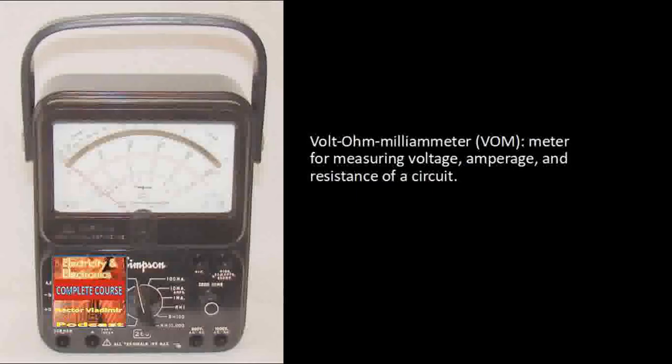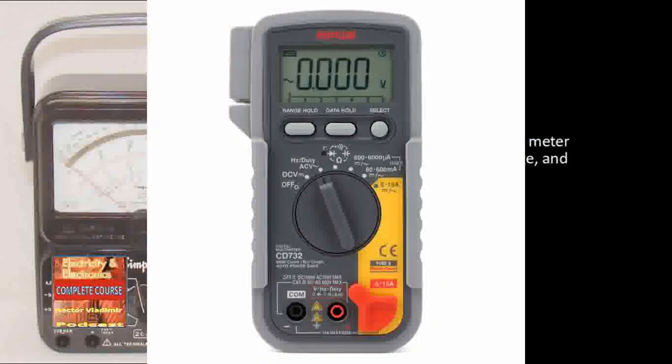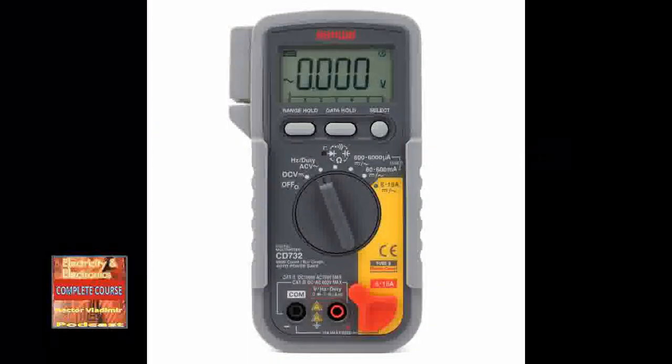On all meter measurements, make a flash check before permanently connecting the meter to the circuit. What does a flash check mean? First, a decision should be made on how to connect the meter to the circuit. Then only the negative lead should be connected, with the positive meter lead left disconnected while observing the meter. Quickly touch and remove the positive lead to the circuit. Did the needle move in the wrong direction? If so, polarity must be changed.